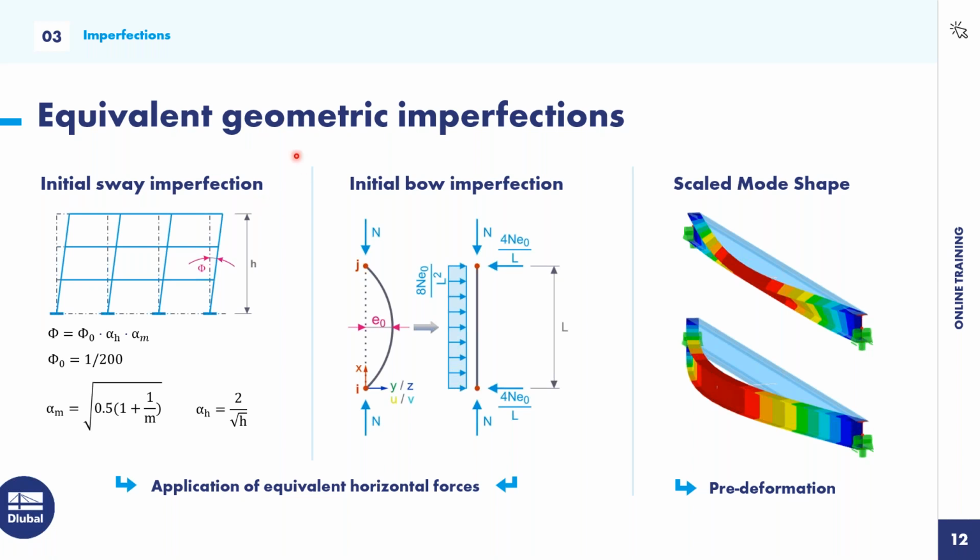So when I manufacture some steel profiles, for example hot rolled sections, it can be possible that some internal stresses appear, and these kinds of effects need to be considered, because what we do the whole time in the structural analysis programs is to consider ideal models, but the reality is not ideal. So in order to consider these effects, we have to apply imperfections.